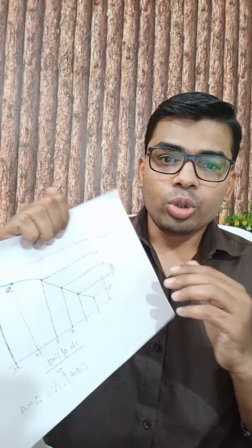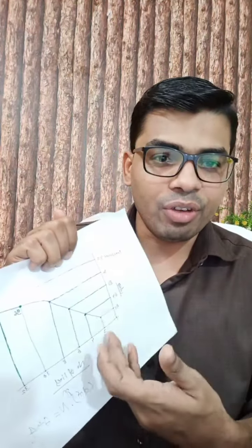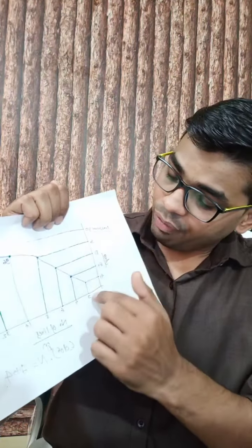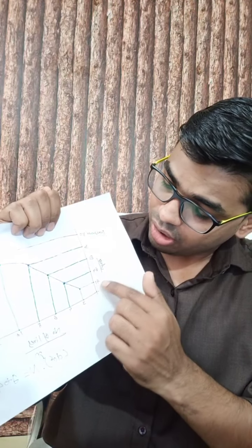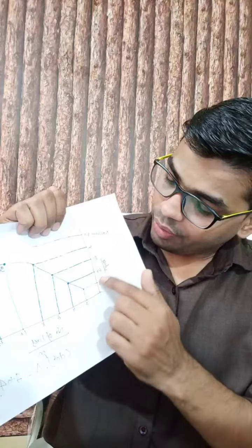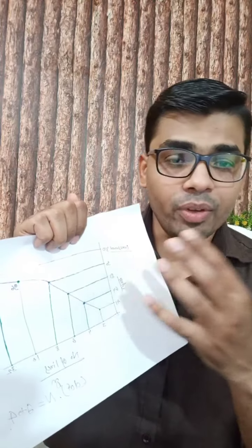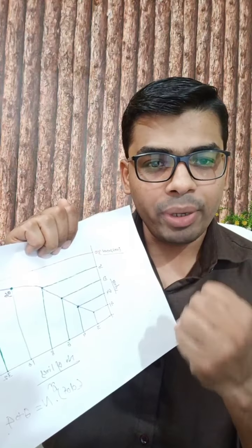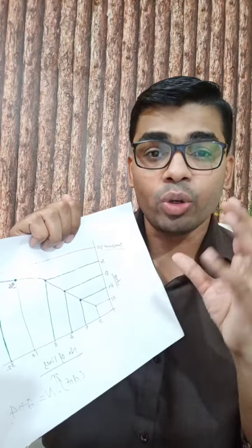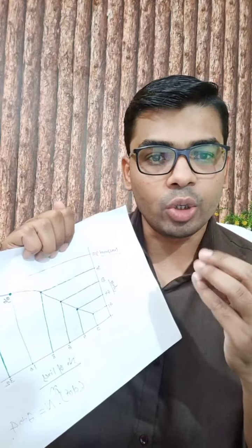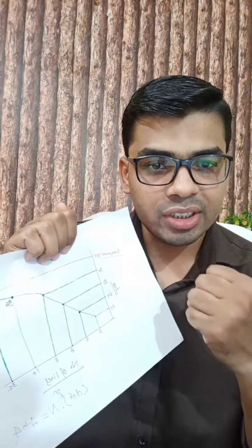So how to decide the element size again, because all of these are increasing, right? Look at this. Can you see the graph here? So if you have three lines, you obtain 41 as the area at 464. As you increase the number of lines, you come closer to the exact solution of 100, right? But again you have to increase the element size. So what you can do, as I said earlier, is make a combination of element sizes, fine and coarse, depending on the critical areas, the hotspots, and the areas where the chances of getting more stresses will come.